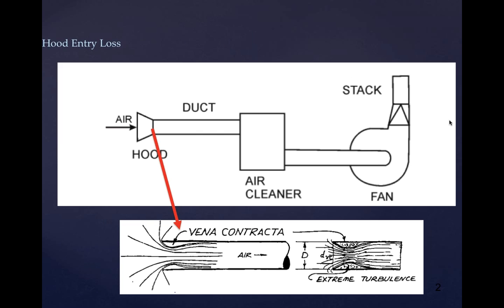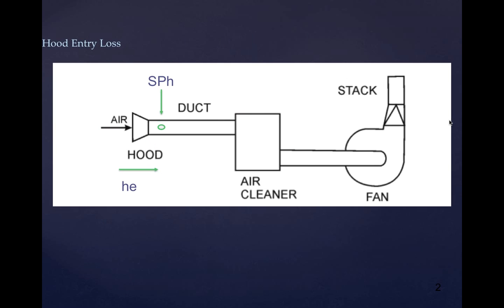If you have a boiler at home, a small boiler in a private home, you'll notice that somewhere the person that installed the boiler probably put a little louver on a window or through the wall of the basement so that air can come into the basement, because it won't exhaust properly unless it has makeup air. So almost any time you see a device like a hood or a smokestack that has to exhaust from a location, you're also going to see some mechanism for makeup air.